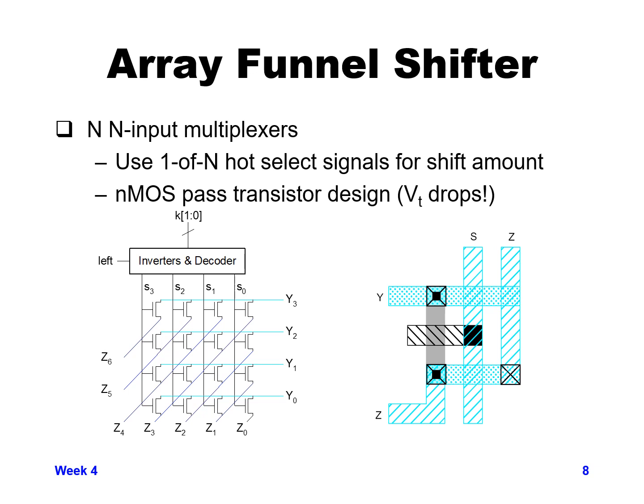So you can see below on the left hand side, they're using NMOS gates, a single NMOS gate, as basically a pass gate / mux type structure. One thing in this particular design, because they're only using NMOS gates: if the z value that you're trying to send through to get your output y value is a 1, it doesn't pass through as well through an NMOS device.